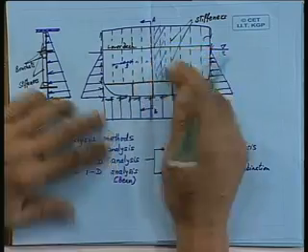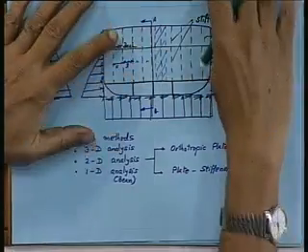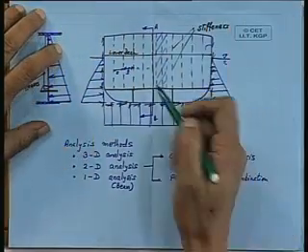Let me bring back this here. See what we did here, we considered a strip out from this bulkhead. I suppose it is visible. Yes, I have taken a strip from here instead of this, because everything, as I said, is uniformly spaced, with the same plate thickness and same stiffness cross section. So, I could have taken a strip from here also.